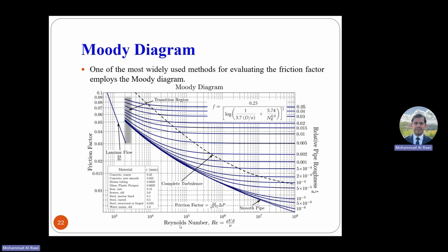Here on the x-axis is the Reynolds number. You have the equation Re, which, as I told you, in other textbooks is Re, not NR. Rho V D over mu: density, velocity, and average diameter divided by dynamic viscosity. That scale is a bit funny because it's based on experimental data. So 10 to the power 3, which is 1,000, and this one 10,000. And then the transitional region is highlighted in gray.